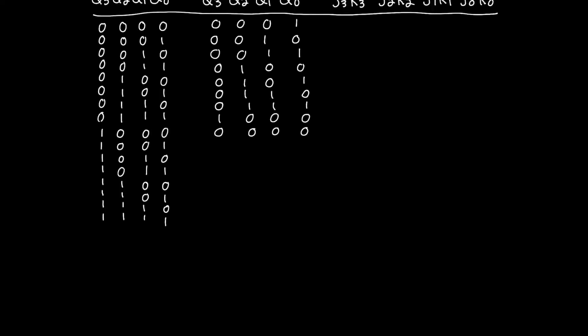Or I can say, you know what, it's really important for me that should I power on my counter and I find myself in one of these invalid states, that I know precisely what the next state is going to be. Maybe I want the next state to always be 0. So as the designer, you have two options here. Now, if you specify a particular next state, then you will have much more complicated Boolean logic expressions in the end for all the control inputs.